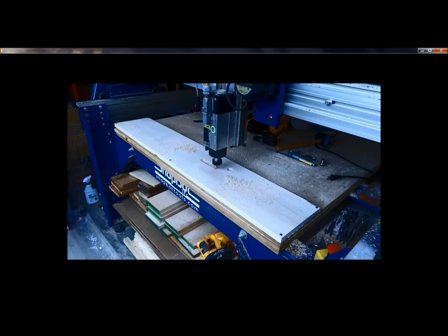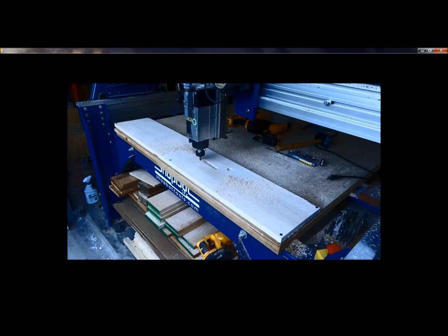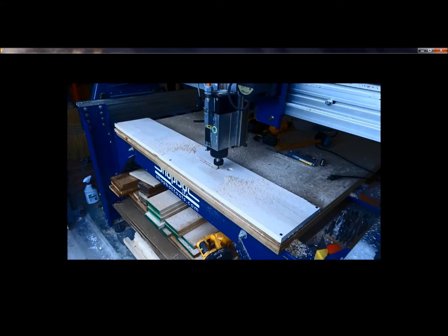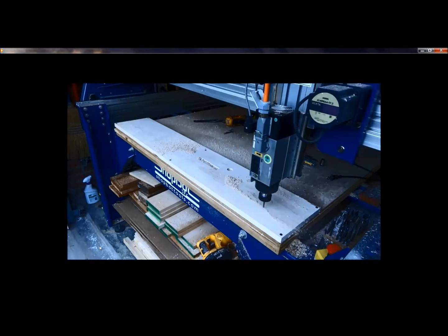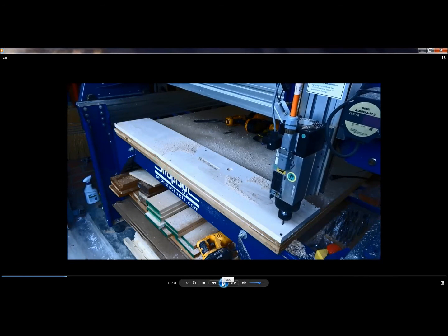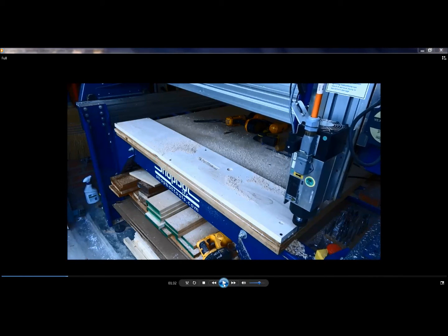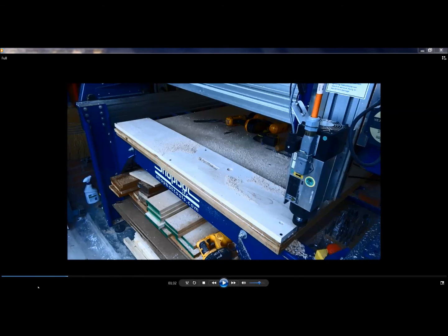completing that depth, and then cleaning out where the ramp was. So the first two was a pocket of 0.5, and then the third cut here is a pocket that's not quite as deep. It's only a 1/4 inch deep, but again, same thing, it had one little ramp. So before I move on to the next part, notice how the machine is now moved off the bit, off the board. The bit is now hanging off here in -0.